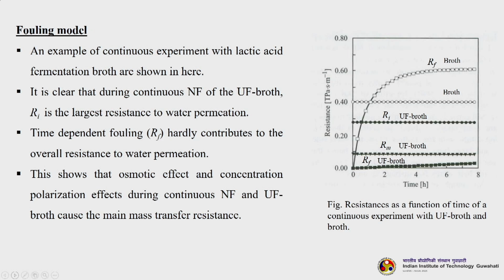So, let us see this particular figure here. So, this is the resistances as a function of time of a continuous experiment with a UF broth. Okay. So, UF broth means ultrafiltered broth. So, an example of a continuous experiment with lactic acid fermentation broth is shown here. So, it is clear that during continuous NF of the UF broth, Ri is the largest resistance. So, this is for Ri, this is for Rm, this is for Rf. So, you can see this.